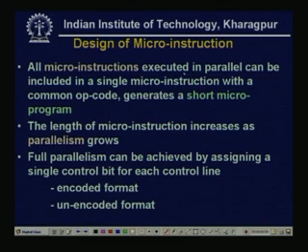The micro operations which are executed in parallel are included in a single micro instruction with a common opcode, and this results in a short microprogram. But the length of micro instruction increases as the parallelism grows. So the number decreases, but the length increases.